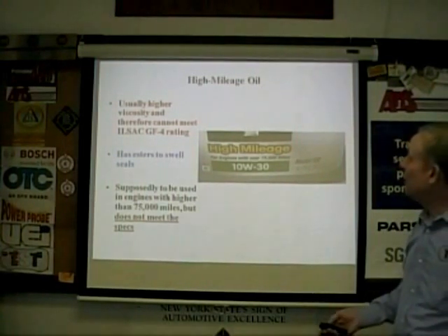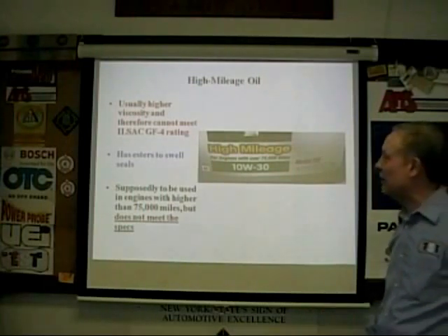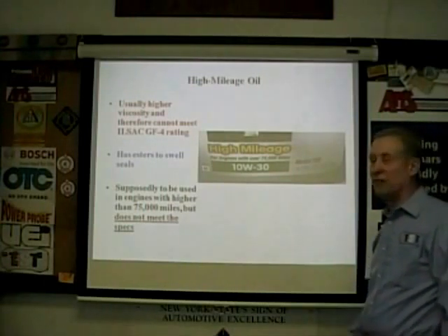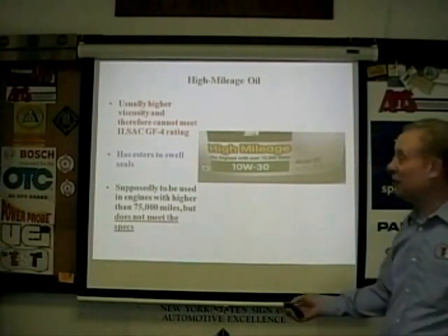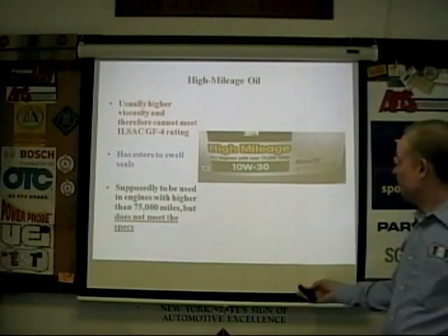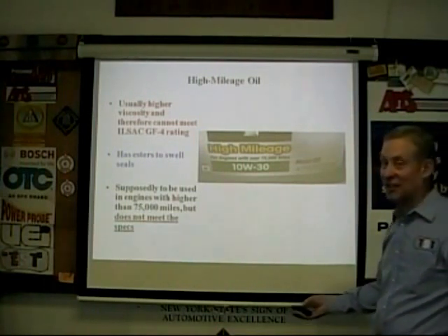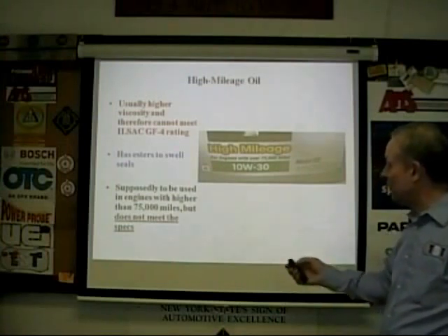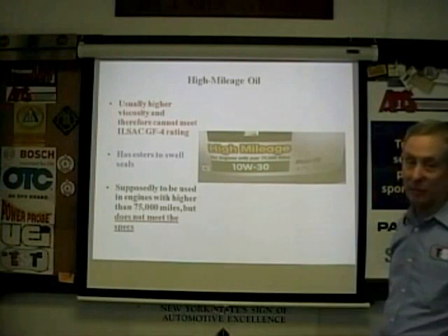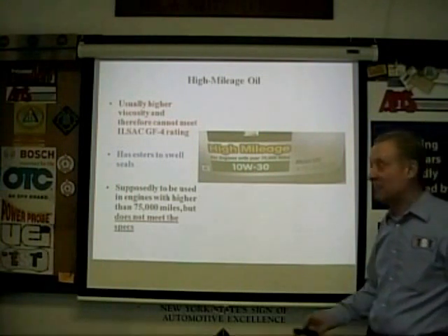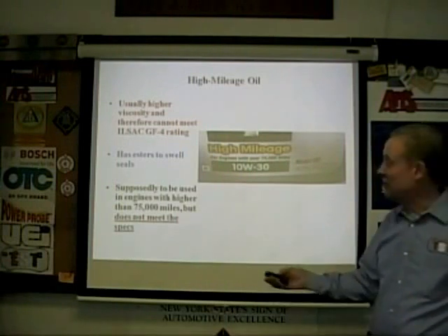All right, high mileage oil. Usually higher viscosity and therefore cannot meet the GF4 rating. It's not going to be as fuel efficient, but it's high mileage. Long oil changes, 15,000 mile oil changes, things like that, are what they're rated for. I don't think it's a good idea. I don't agree with it. They have esters in them. They swell seals. You can end up with permanent damage. Eventually, those swollen seals will split, and you'll end up with all kinds of mayhem.